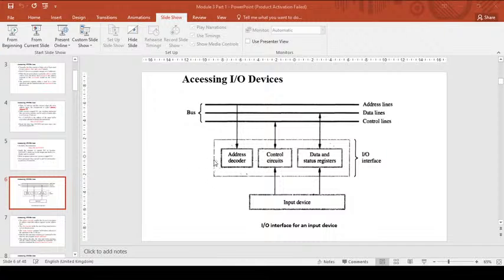If the character entered is the same as the carriage return, that means the end of the line is reached. If it is not the same, then go to wait k, read the next character, display it, store it and compare it with the carriage return to check whether the end of line is reached. So this will go on till the entered character present in R1 becomes equal to the carriage return. So did you understand?